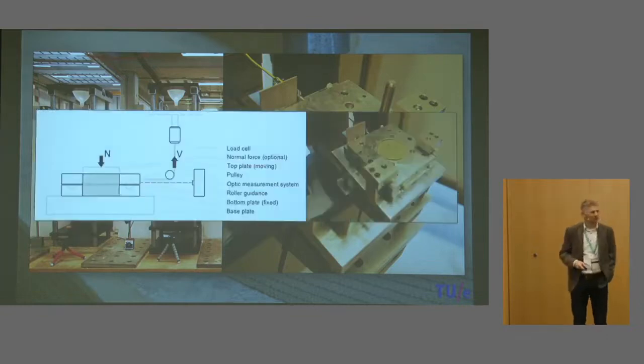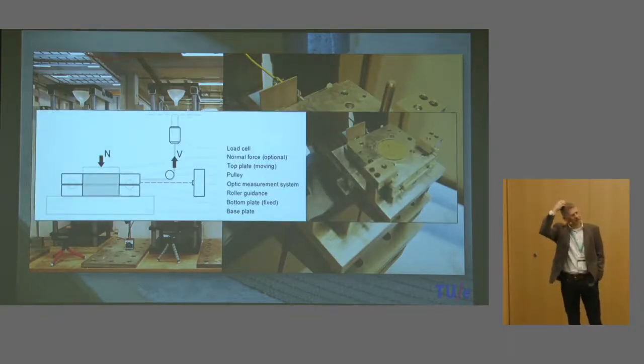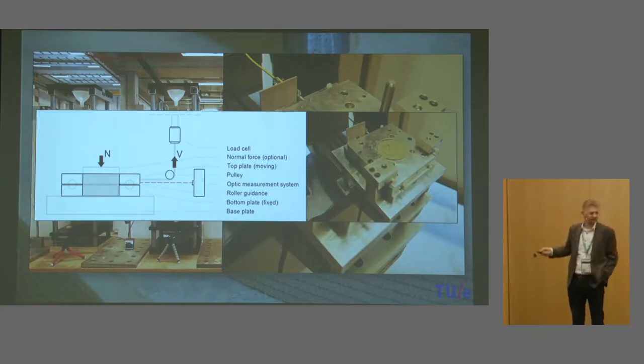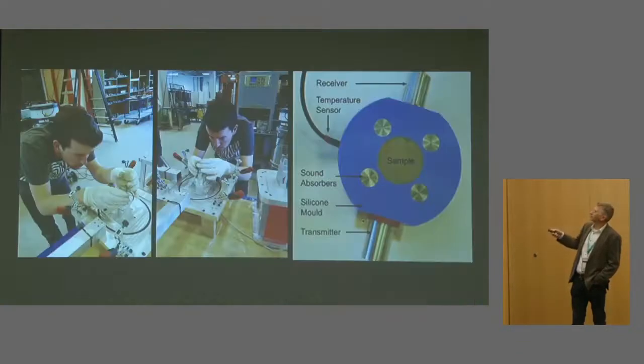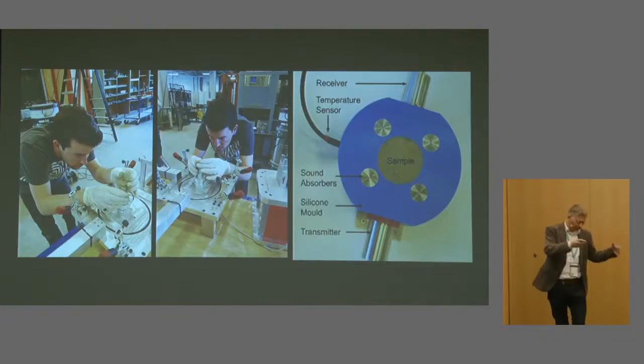I don't want to go too much in detail, but for the structural engineers amongst you, if I have compression and I have shear, I can make a Mohr-Coulomb kind of a model as a failure envelope for my concrete. And if I put all of that information into account, it's a really hard work. I have to do two tests, compression and shear, and combine the data. So we figured out, let's do a triaxial test, as they do in soil mechanics. You can do everything in one test only, and you can test it on the material as it comes from my hose. You don't have to treat the material up front anymore.